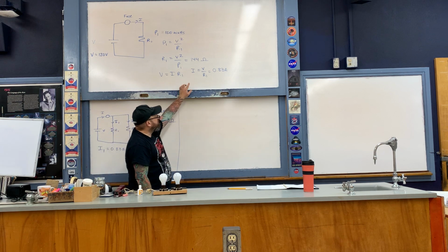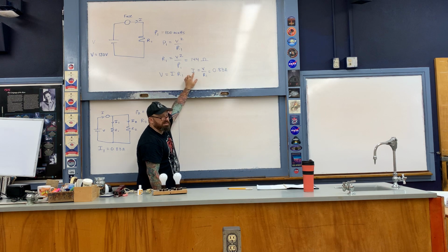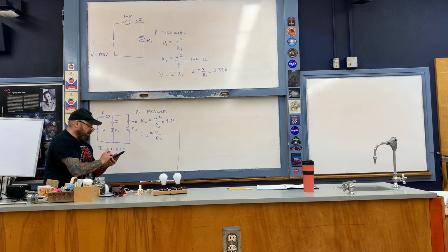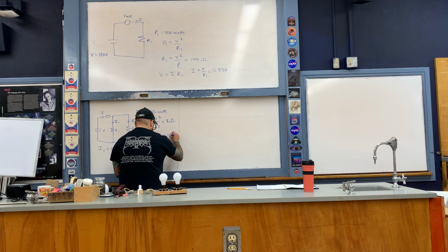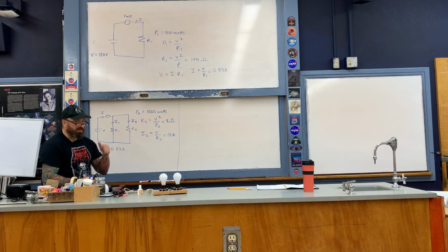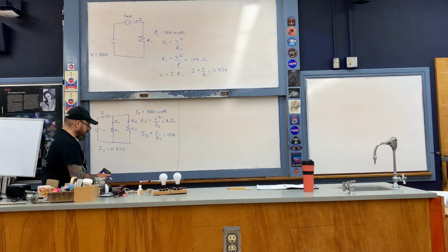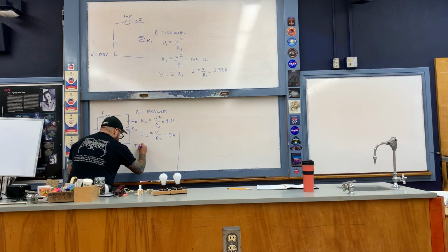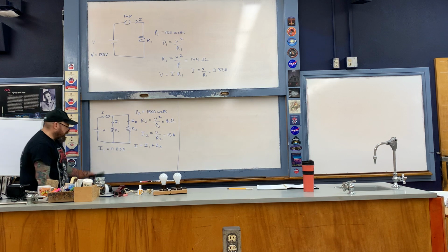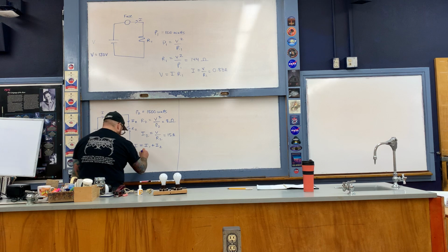And then from there we can calculate the current, in this case I2. It's going to be the voltage V divided by R2. The voltage V is once again 120 because this is a parallel circuit, and then divided by 8. And this comes out to be 15 amps. So notice that the current being drawn is really starting to creep up as we turn more things on. Therefore, the total current I is now I1 plus I2. So the total thus far is 15.83 amps.